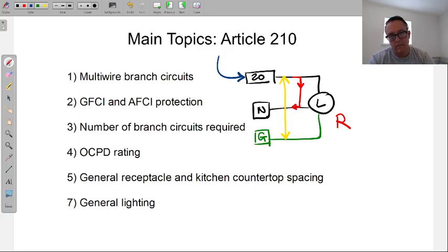That's all it does. Ground fault circuit interrupter, or GFCI, or GFI. A lot of people cut out the C, just easier to say. GFI is the same as a breaker. A breaker will trip if there's a short circuit or if there is a ground fault. The breaker will trip. It'll shut off the circuit. But that takes about 1 second to 2 seconds for the breaker to trip during a short circuit or a ground fault.